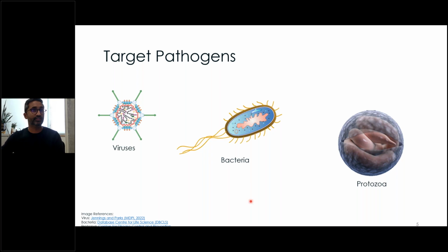Just as a counterpoint, UV, for example, is actually quite good at getting into protozoa because those light rays, those UV rays, they can actually get right through the wall of a protozoa and attack what's going on inside without much difficulty. And so, for that reason, protozoa actually are quite susceptible to UV.